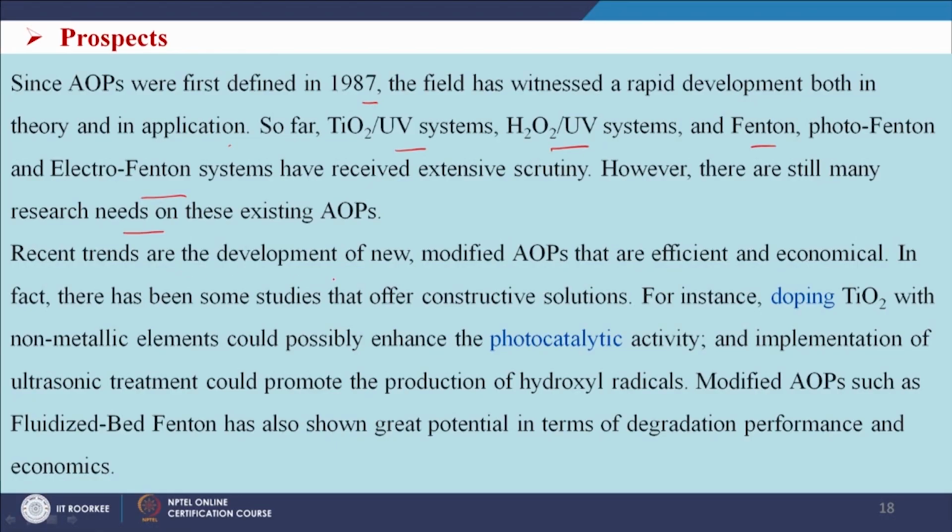Recent trends are the development of new modified AOPs that are efficient and economical. In fact, there have been some studies that offer constructive solutions. For instance, doping TiO2 with non-metallic elements could possibly enhance the photocatalytic activity, and implementation of ultrasonic treatment could promote the production of hydroxyl radicals. Modified AOPs such as the fluidized bed Fenton process have also shown great potential in terms of degradation performance and economics. So, up to this in this class, thank you very much.